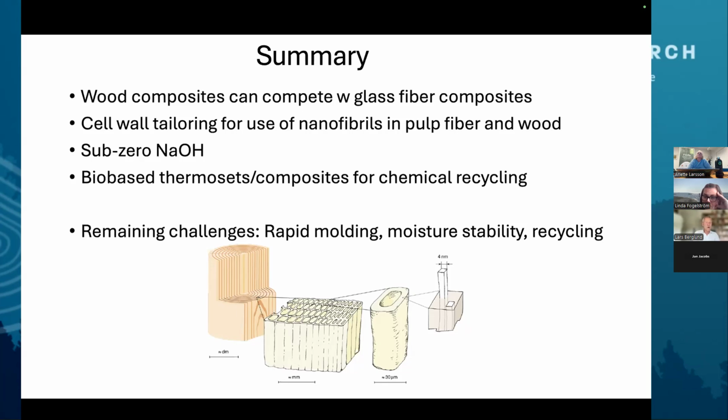Yeah, the main problem here is that this acrylic, the Plima acrylic, is a thermoset, and our dilemma here is a little bit that we have many criteria to meet. We need optical transmittance, we need to match the refractive index, and it's not ideal to have a large aromatic side group here. It helps refractive index, but it messes up the ductility of the polymer.